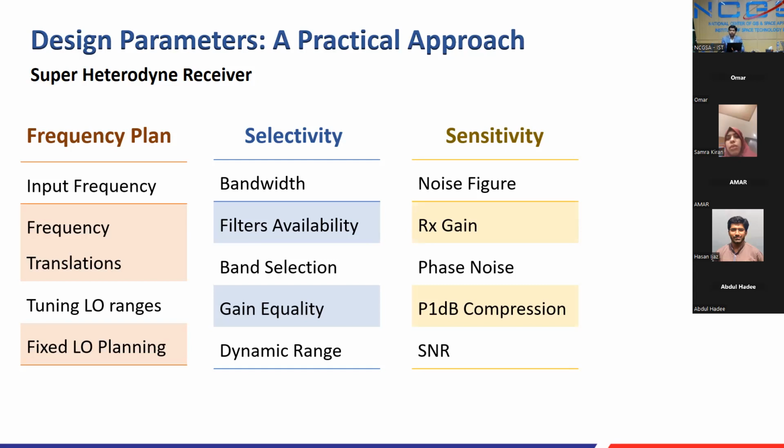Then there is phase noise. Phase noise, I will have a practical measurement slide on that as well. Phase noise is actually, we know PLLs, phase lock loops. We know PFDs, phase frequency detectors. What actually happens is the phase frequency detector, and we have clock sources, TCXOs, OCXOs, temperature compensated or oven controlled crystal oscillators. So with those clocks, when we drive a PFD, naturally there is some murmuring or jittering noise over the clock sources. These clock sources actually contribute toward the phase noise.